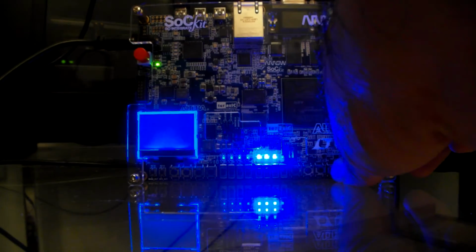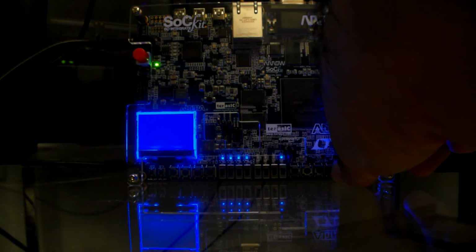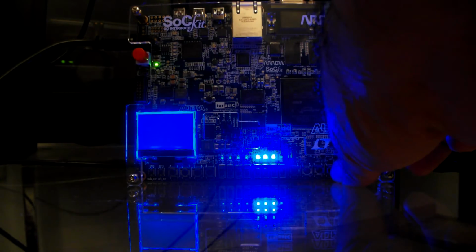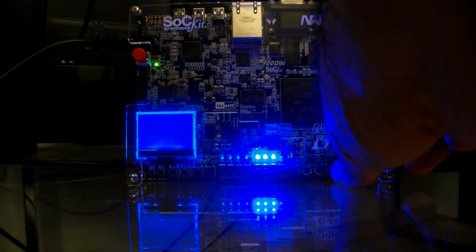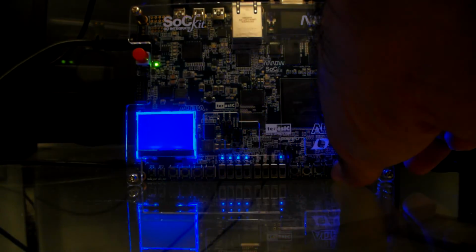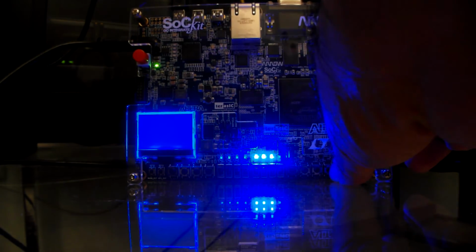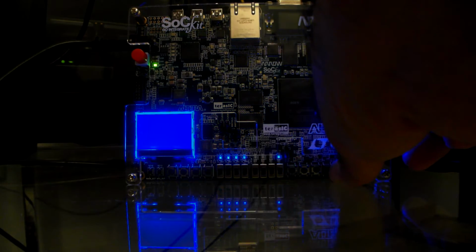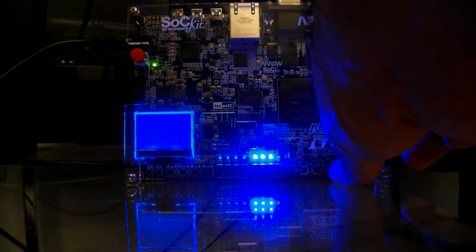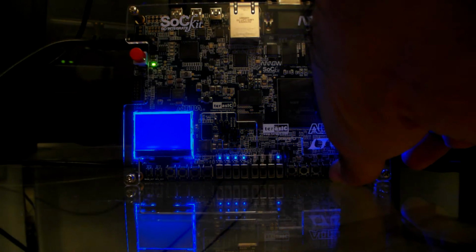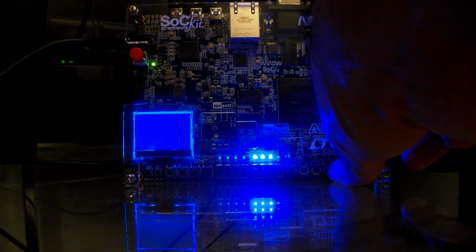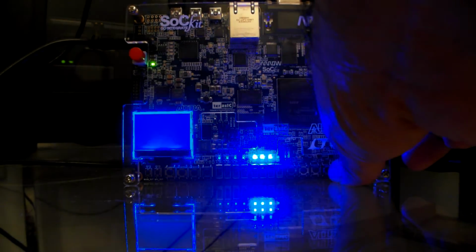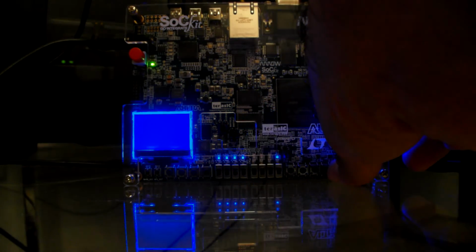And I have in fact the reset button here on one of the push buttons. If I press the reset button, I can make them synchronize, or better to say, they will start from a known state. And this is kind of important when you do partial reconfiguration, because when you partially reconfigure a unit, obviously after that you need to apply a reset to that unit so that it starts from a known state. Okay, so here is the reset button.